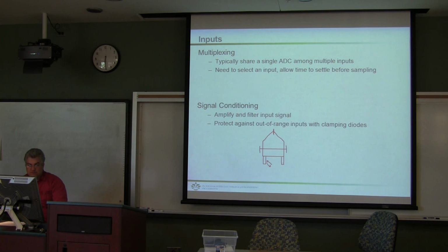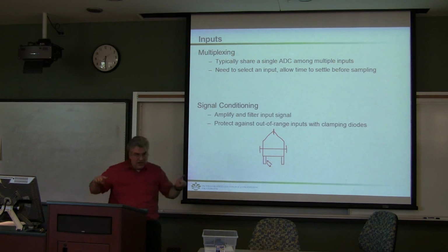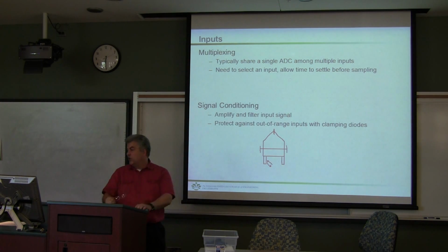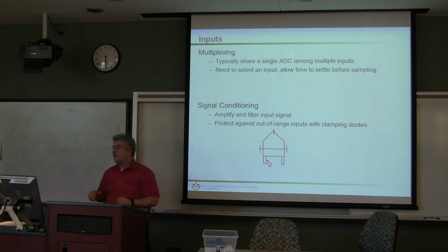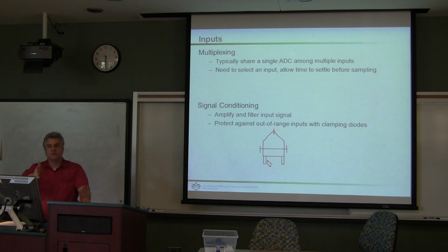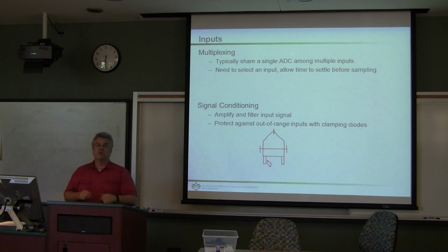And based on the value of that reflection, you'll get a different voltage. Well, you've got two of these. You've got one here and you've got one here. So you'll have two sensors that will go in, and typically your hardware only has one A to D converter. So what the processor will do is take time. It'll measure one, then the next, then one, then the next. It's able to identify, I'll take this device first, measure it, next one, and then you could use that data in your LabVIEW programs for your Danny robot.